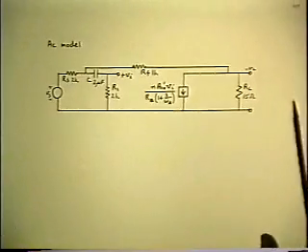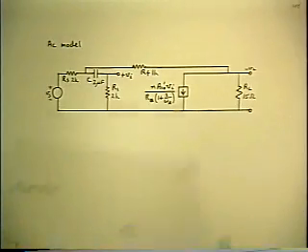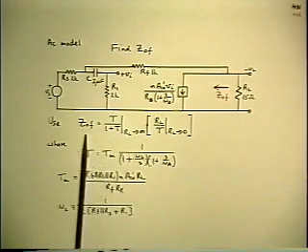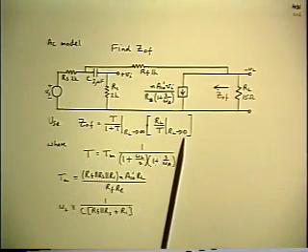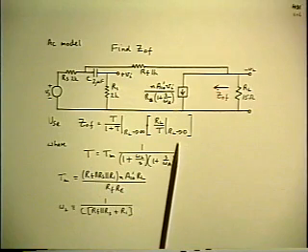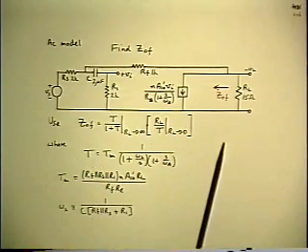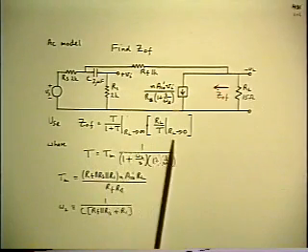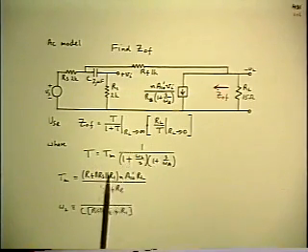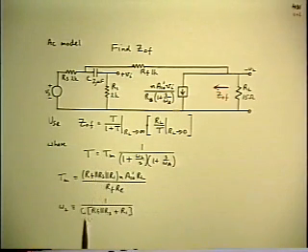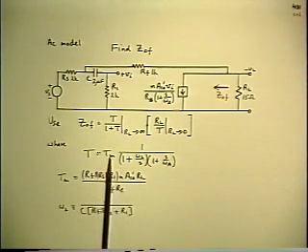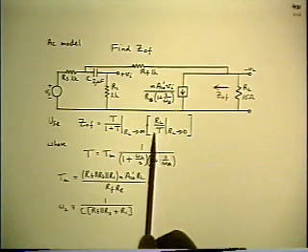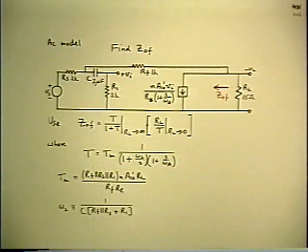So back to the model. Let's use the version which refers back to the loop gain only, since we don't care what the open loop value was anyway. All we need to substitute in this is the loop gain expression, which we've set up, and I've summarized it again down below. It has a mid-band value, and it has two poles. So all you have to do is evaluate this limit and the factor in front.